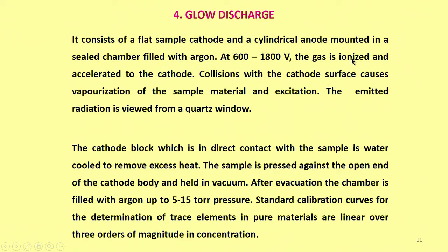So, that is how you see, if you go to MG Road or somewhere, you see neon lights nowadays, LED lights, most of them are generated from low concentration of argon gas or neon gas. Neon lights, you must have heard, most of the neon lights are operated like that. So, basically it is a glow discharge. It is not something which is high technology, nothing is high technology in this, and at 600 to 1800 volts the gas is ionized.